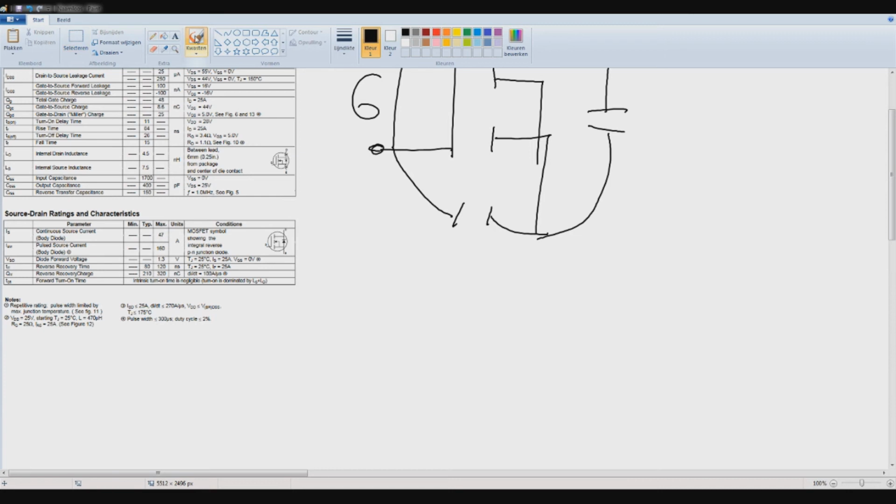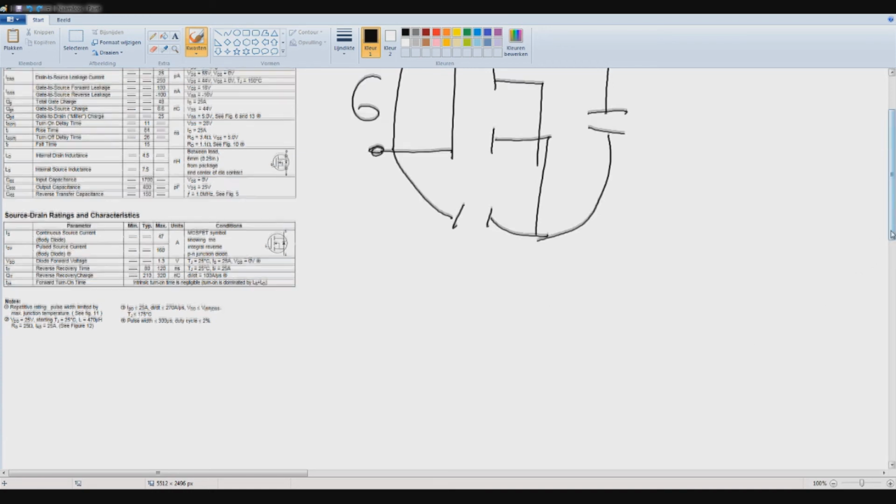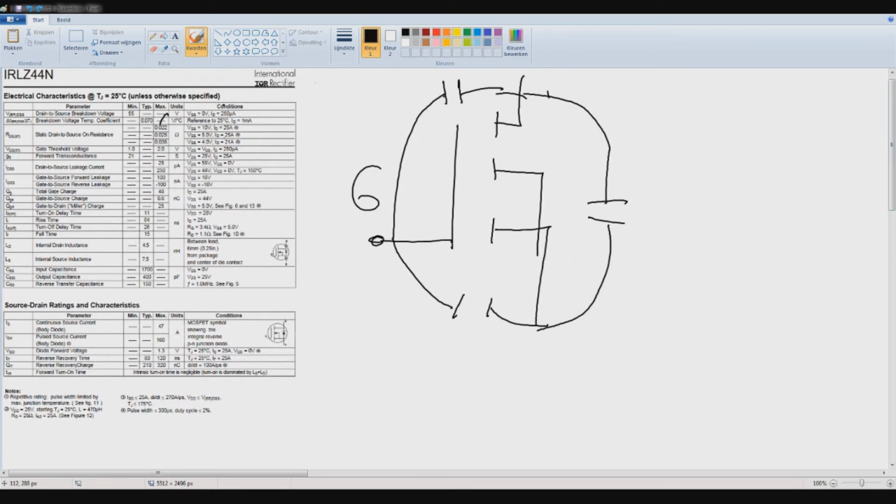2.4 amps is a lot, and 20 nanoseconds is also very little. As you can see, it doesn't even turn on that fast. Or it does actually turn on, but it doesn't rise as fast. Which is a part for later, but let's first look at the next value, which is the gate to source charge, which is this charge over here, this capacitance.